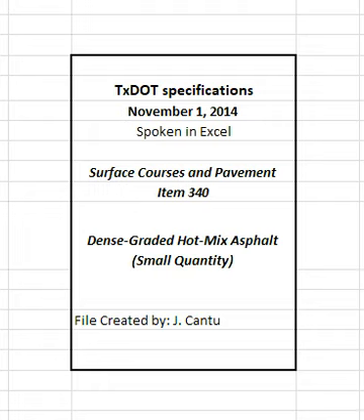Certify compliance of the RAS with DMS-11000, Evaluating and Using Nonhazardous Recyclable Materials Guidelines. Treat RAS as an established nonhazardous recyclable material if it has not come into contact with any hazardous materials. Use RAS from shingle sources on the department's MPL.